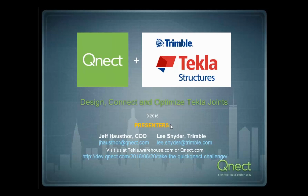We actually had a situation where there were mandated connections. The fabricator working with the connection engineer ran it using the mandated connections, but then changed a couple things in order to make it cheaper. And between the connection engineer and the fabricator, they went back to the EOR and said, is there a way you can change these few things? And in that case, the EOR was comfortable changing the mandated connections, and it saved the fabricator tons of money.